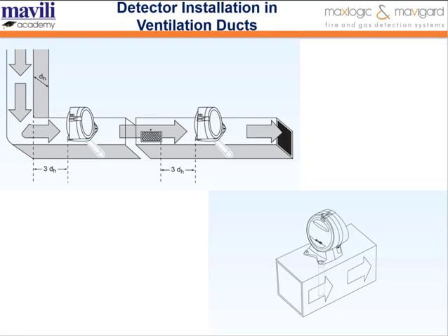The second important location is where air enters the duct system, such as near ventilation grills or intake points. Even if the air already flowing through the duct is clean, smoke could enter the system from these intake points. Therefore, another sampling detector should be installed at a distance of 3 times the duct width from the air entry point. This is the basic principle behind detector placement in ventilation ducts, ensuring that smoke carried through the ventilation system can be detected as early as possible.